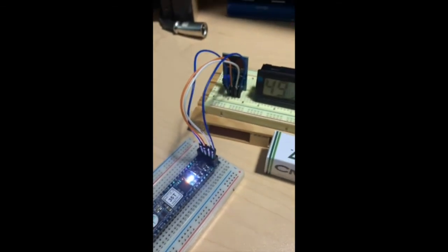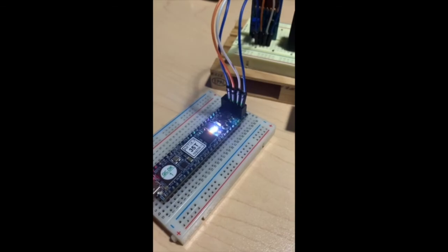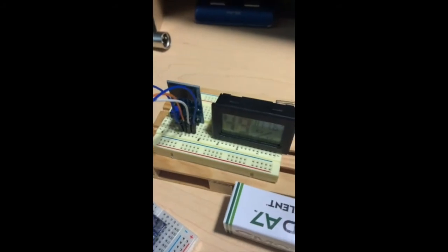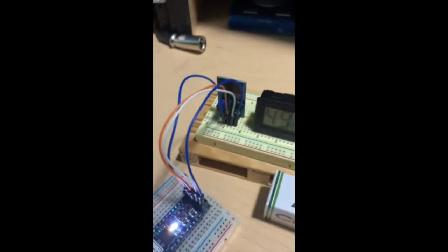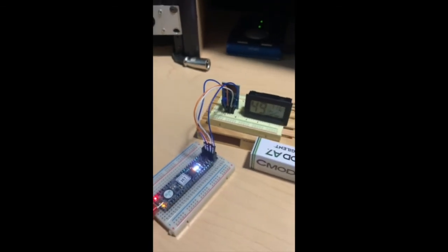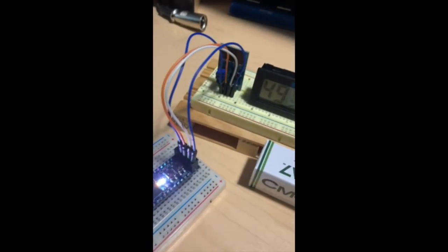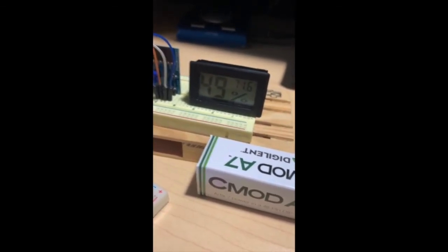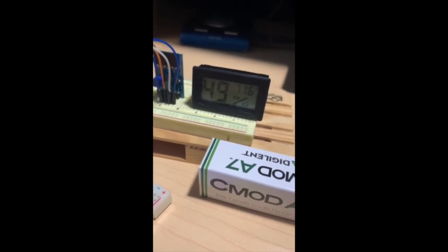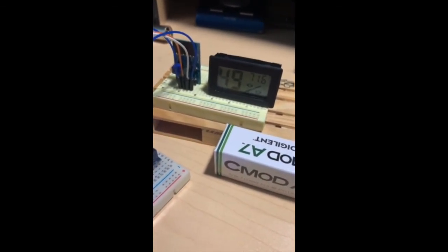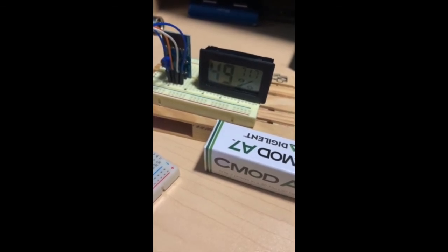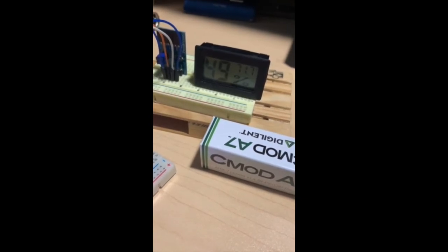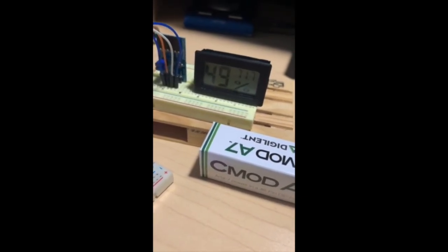But we did notice that while it was connected, the warmth of the board was actually affecting the temperature readings of the room. So we went ahead and removed it and connected it separately, so that the temperature being displayed shows properly. So here's a little sensor that I used, and this little guy is actually pretty accurate. I tested it against a Fluke sensor, a more expensive sensor, a couple weeks ago, because I wanted to know what the humidity and temperature was in this actual room where I'm at right now. And this guy was spot on.